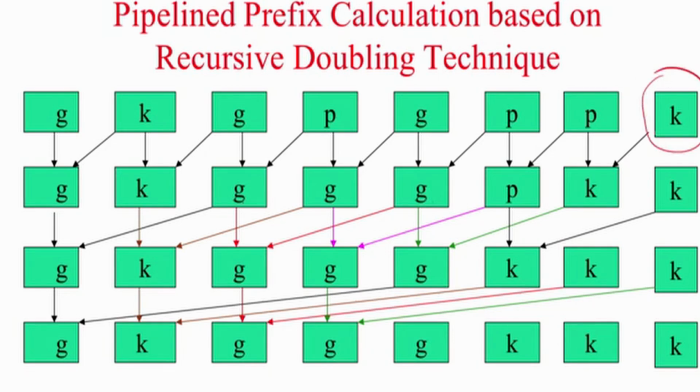Right. Still we will do it in log n time, but I do not want to reuse this unit; I am replicating it. Since I want to do an 8-bit addition, at least I need 3 stages, log of 8 is 3, right. So I am replicating this 3 times, but I could reuse the same unit again for the star, but then I need multiplexers to keep routing it. So this is very easy for me to do, but there is another advantage of doing this also.